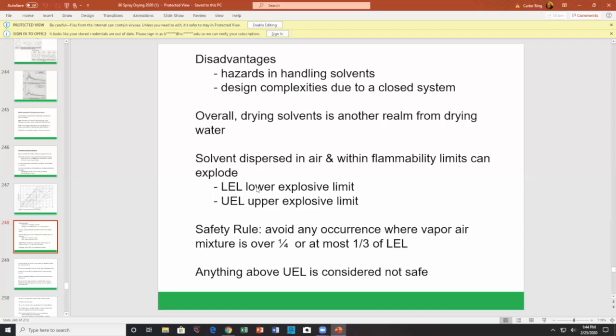And then people came to work and started up the lift. It was a gas powered high lift. Because the carbon tet layer was still below the ignition, there wasn't any accident. However, they left the machine on during lunchtime. The carbon tet got raised up to the level of the ignition, since it was gas powered, and the system exploded on them. So whenever you're dealing with gas, you've got to watch out. It may separate on you.